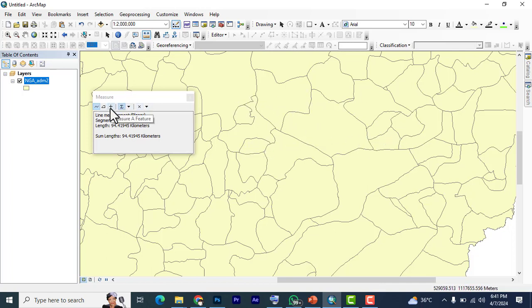But if this feature is selected, anything it measures, it will measure as a polygon, and it will measure other things like the areas, perimeters and any other features that are within them. But we are having measure line here. This is measure an area. So if I check on this and I click on this, it's still going to bring out, it wants me to go around, which is stressful enough. That's why we have the measure a feature, which you can easily use, once I click like this, it will measure.